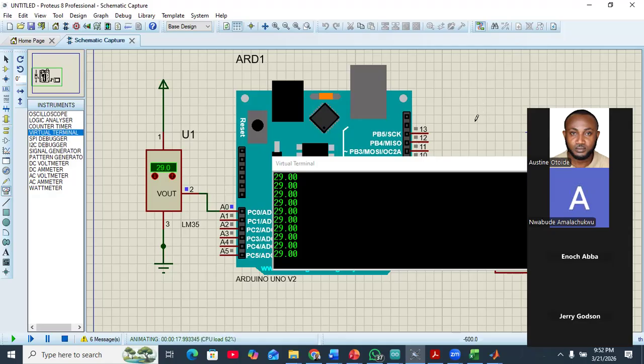You have gotten an approximate value of your result by instrumentation. Fine-tune your instrumentation so that you get the appropriate result. What will help is to have a reference instrument. For example, if you are trying to build a temperature device, you should use another thermometer as a reference point to be sure the one you are building conforms to the temperature.